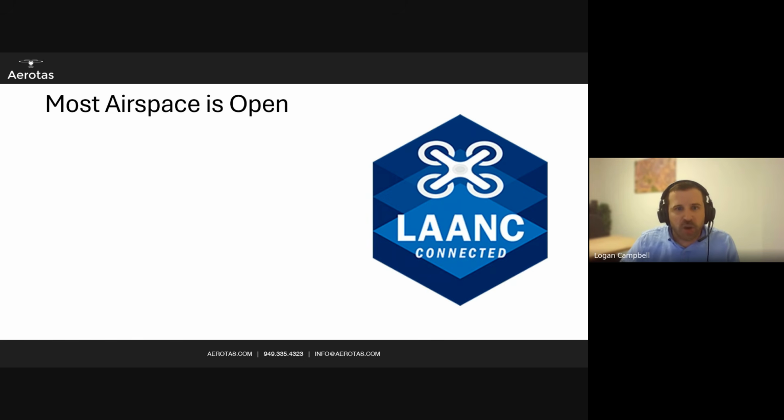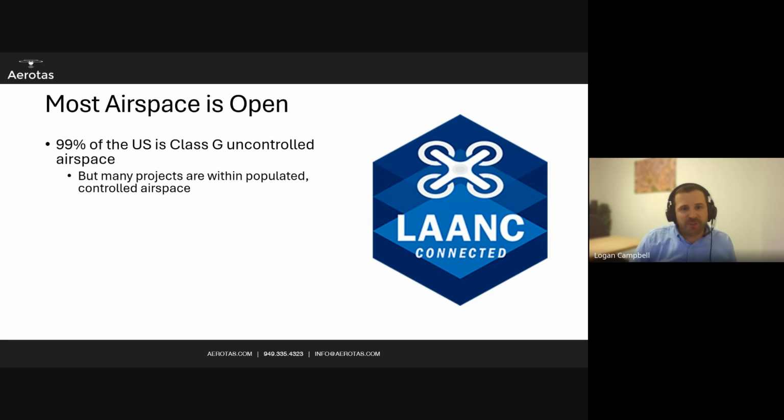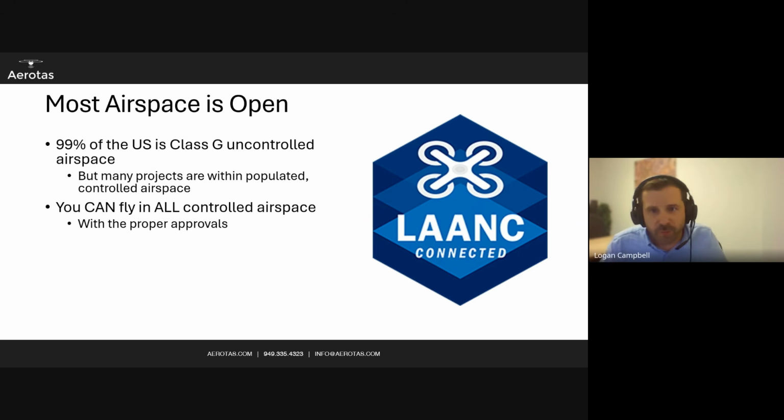So first of all, the most important thing to know is that most airspace is open in the United States. 99% of the US at surface level is Class G uncontrolled airspace, but of course, many projects are within populated or controlled airspace. It is worth noting that you actually can fly in controlled airspace if you get the proper approvals. And in just a second, I'll go through all of the different levels of approvals and the easiest ways to go through and get them when you need to get them.